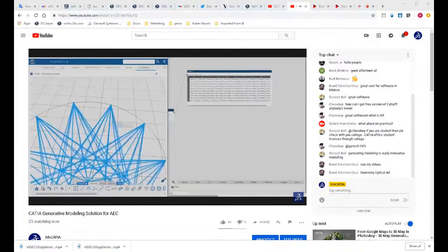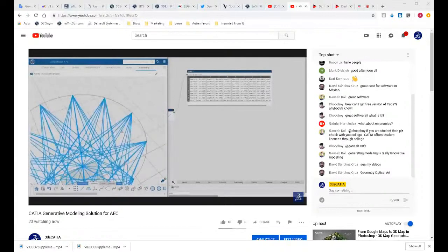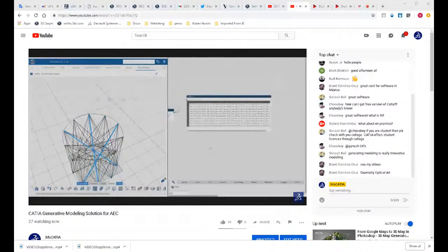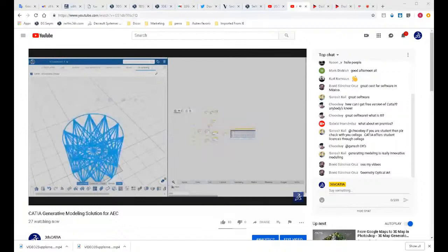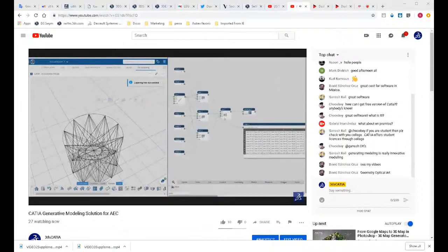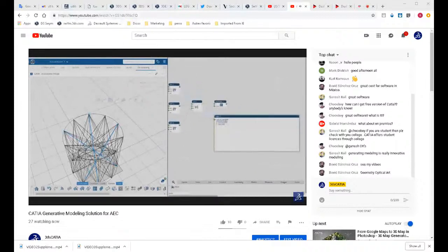So here I'm going to isolate different elements one by one. Different elements on different lists have nothing to do with each other, but I need to extract them for some reason, because you have a lot of exceptions in parametric design. So here I'm going to create an assembly, and you can see that it created a sublist in order to extract those lines. Out of those lines it created a sublist with the right indexes in the first and second dimension. So this is absolutely key in parametric design, working with lists.